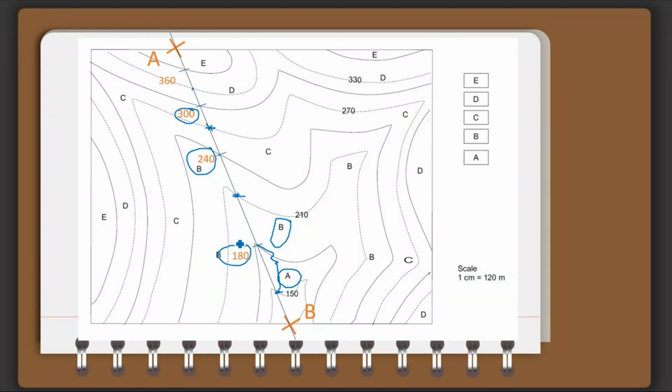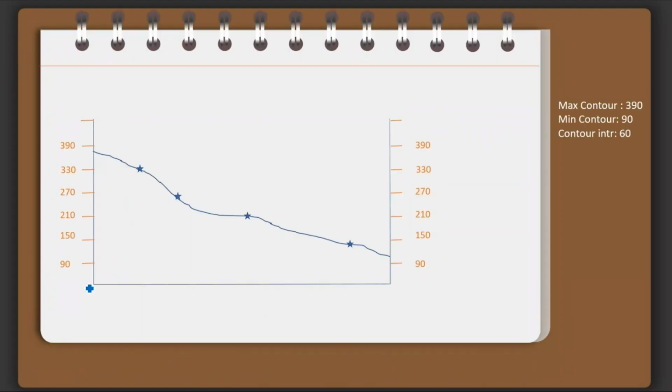So I will draw that line on the geological map or geological section. So 180 means this is 150, this is 210, so 180 will be somewhere here. So I draw that line, and I make sure that line doesn't go outside the surface. So this is to be drawn till the surface only, because outside the surface, if the area has already gone, there is no rock seen.